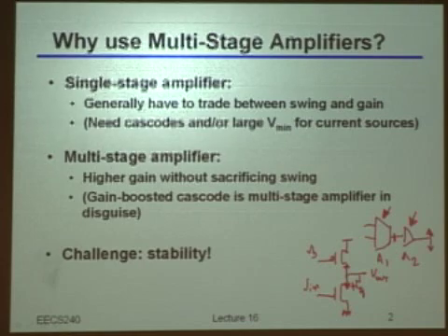Of course, if you put more power there, then you can compensate for this eventual delay that you get. And that also depends on how much gain you have. If you spend power in the gain bandwidth of the two stages, how much gain do you need? If you can trade gain for bandwidth, then you can still go faster. But those things have to be seen on a case-by-case basis. But indeed, stability is a big issue, because you get a lot of poles, as